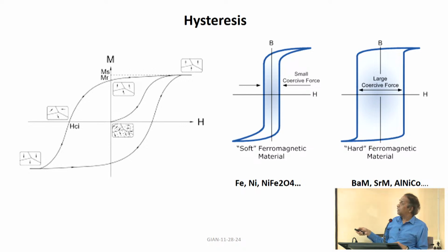The magnetization increases until you reach saturation, where all the domains are oriented in a particular direction, which is the direction of the field that is applied to it. Then you go back and the magnetization will decrease, but when you hit 0 field, it does not quite go to 0, because some of the domains are left with partial orientation parallel to each other.